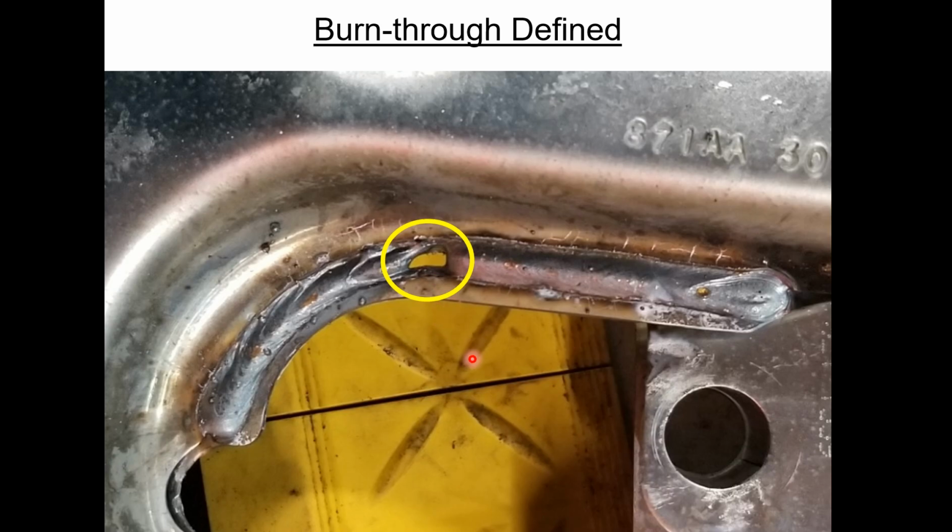I want to talk just momentarily about grinding, because it's an important aspect. If you use a grinder on a part, you don't hit anything but the parts that are supposed to be hit. And that is not a buffing disc, not just taking a little bit of the spatter off. If you're cleaning like that, that's different. But if you take a grinder with a hard disc that is meant to remove material, you have to stay away from everything, especially the zinc coating, because if you bump into that, you thin it out for one, and you remove the zinc coating for another. We don't want either one of those things to happen.